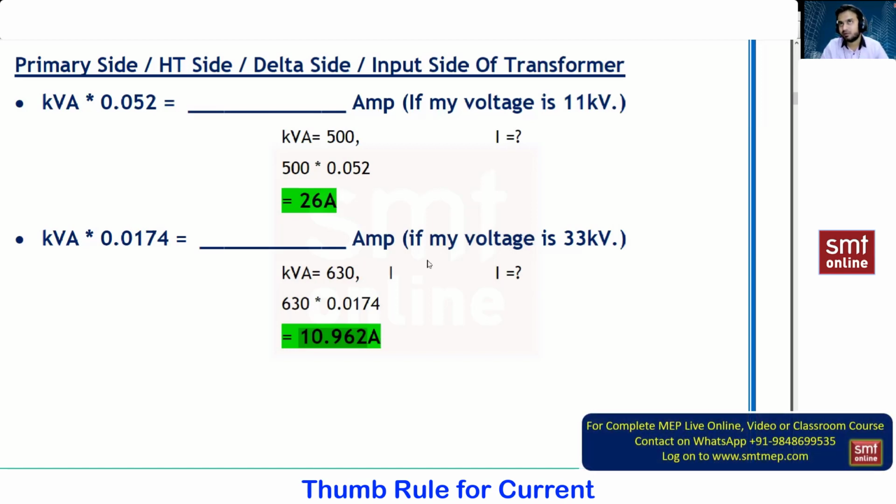Now one more thing you have told me, that till how much amount of value this will take, this much amount of current. Like they have given something like 1 ampere. Always remember that during the initial time, for a fraction of a second, the value of current will be high, because nowadays every light is inductive in nature. Incandescent lamps are totally outdated, the bulbs we used 10 to 15 years back. As we have LED lights, CFL and FL lights, we have a choke, a ballast, and a driver circuitry. We have some inductivity, so initially the amount of current will be high.